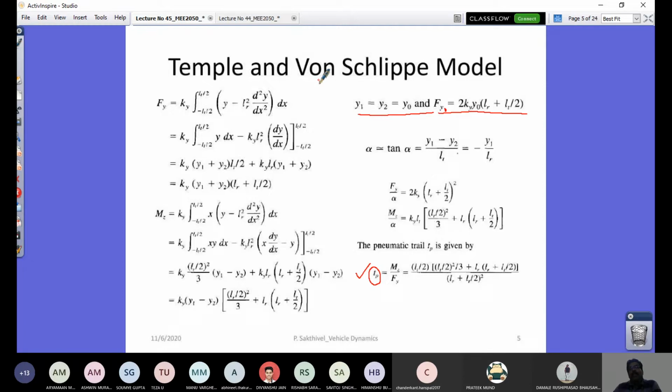So side force is because of the physical phenomenon, slip angle, and braking effort is because of the phenomenon called skid. So the resultant force of your longitudinal force and the side force depends on both slip angle and longitudinal skid. So how do you account for such a model is what is a very complicated model.